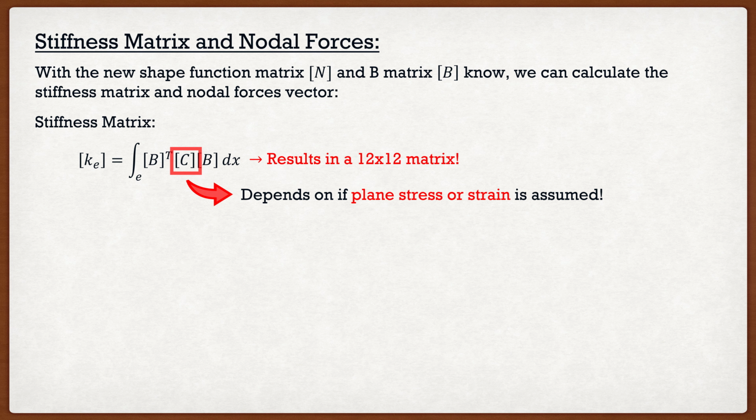So this is one of the things that we're going to have to try and figure out when we're dealing with our own finite element program. And this is also one of the things that there's not always a set answer in. The question is, do I use more linear elements because of course they take less computation time, or do I use fewer quadratic elements? They will take more computation time, but in the end there's going to be that trade-off where you get that increased accuracy. So that's one of the things we're going to have to figure out later on in the course.